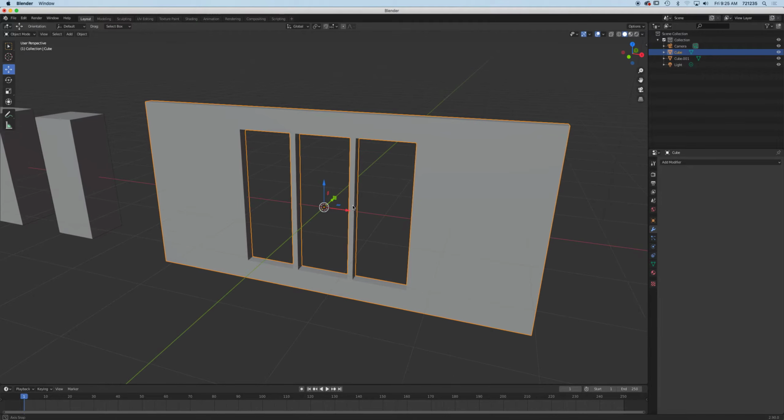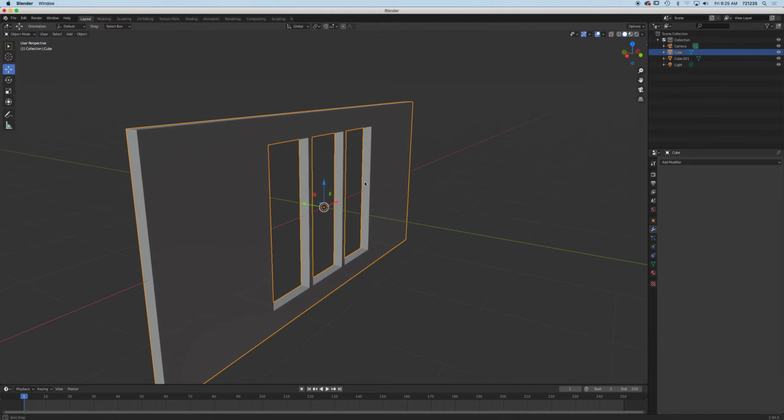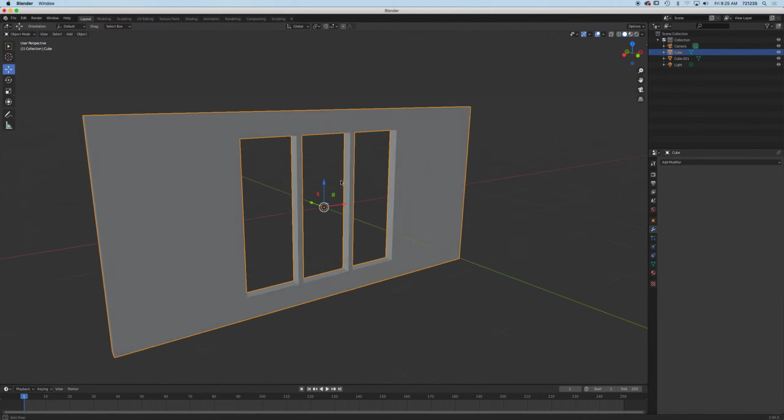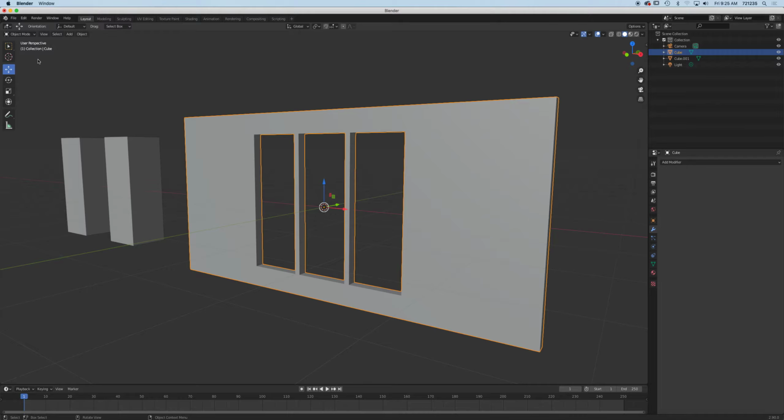So that's Boolean operation for you. Okay, and then there are limitations though. If your cookie cutter is of complex shape, then you'll pay that price. Or if you happen to hit a certain line or an edge, and it doesn't Boolean right, it's not always perfect, but simple stuff like this, it works pretty good. All right, so let's do one more. Semi-practical, okay? I wouldn't call this a practical example, semi-practical, all right?